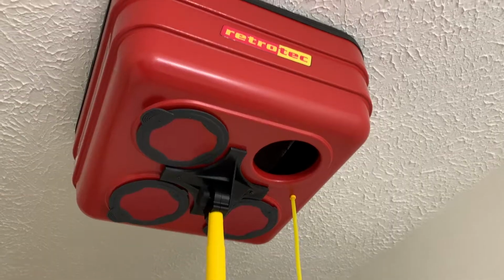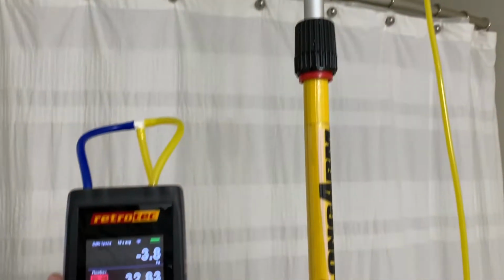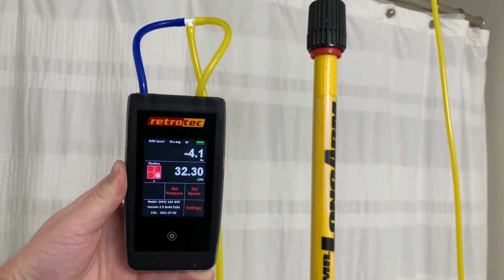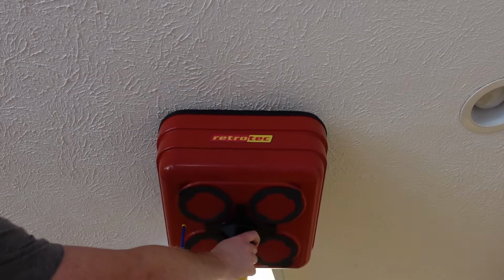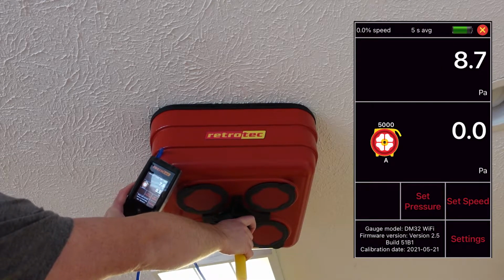And of course, you can also use our flow box as a pressure pan as well, with all 4 holes plugged up. Flow box is an exhaust fan flow meter, so with some of the holes open, you can use it to measure flows in bath fans, some room returns, whole house ventilation, some kitchen exhausts, anything that pulls an exhaust like that. But like I said earlier, with all 4 holes plugged up, you can use it as a pressure pan, so it's kind of 2 tools in one.